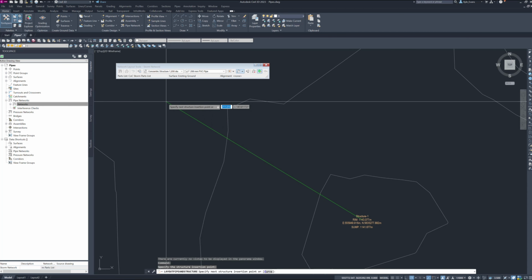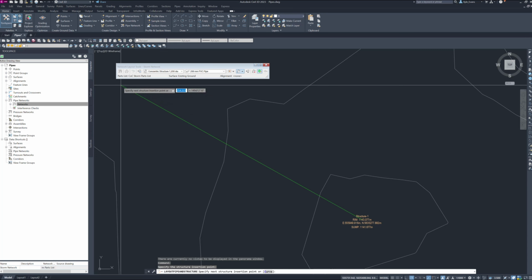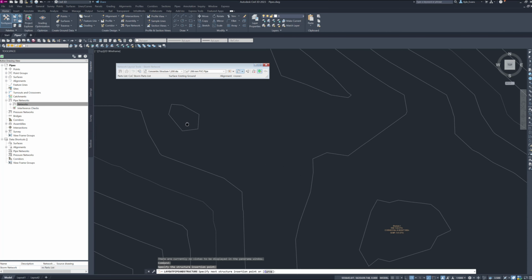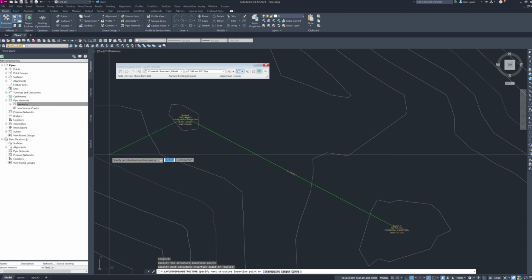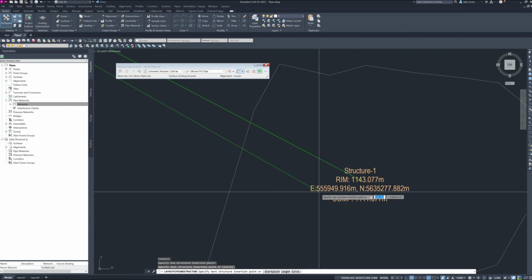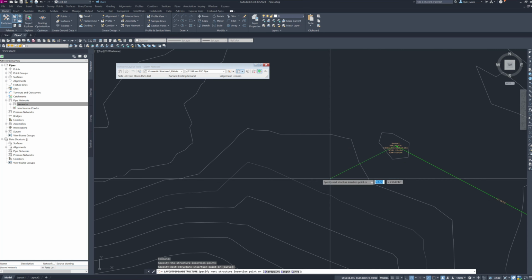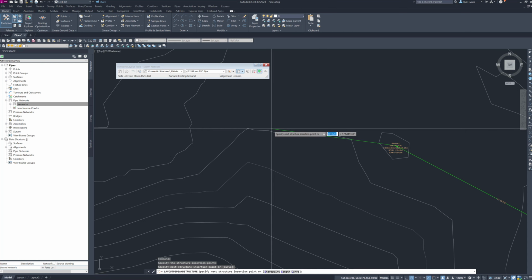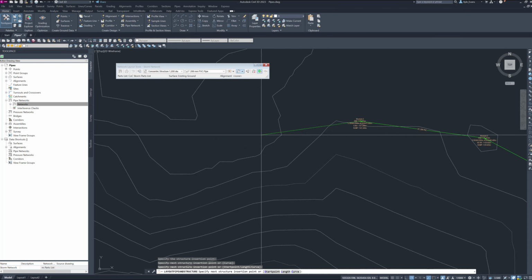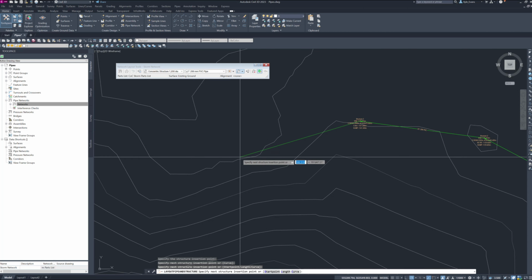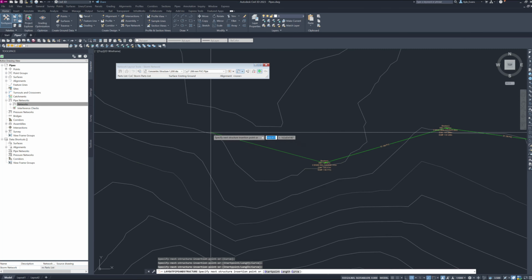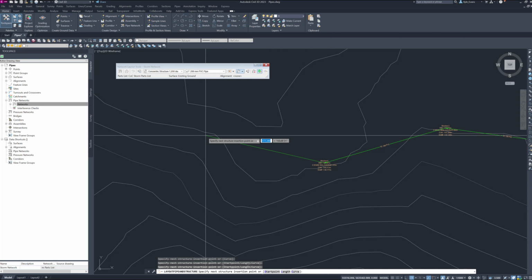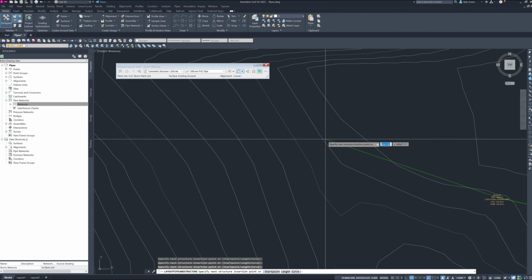So I'm going to make sure to violate my 185 meter maximum rule and go with, we'll do 360. So I'll select somewhere over by this next circular shape contour. Now the labels haven't updated because I haven't finished the command yet. However, I'm going to carry along and look at the distance in my dynamic input window there, and I'm going to keep it roughly 185. So that's not giving me a warning. And I'm going to place in 5 or 6 manholes just so we have some in here we can take a look at. And again, if they're not exactly where mine are, that in and of itself is okay.